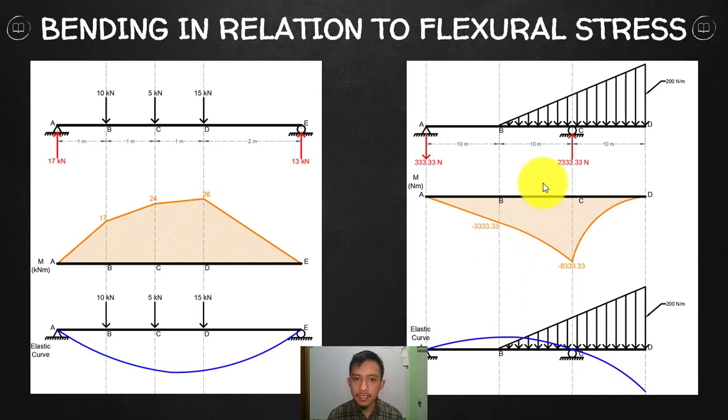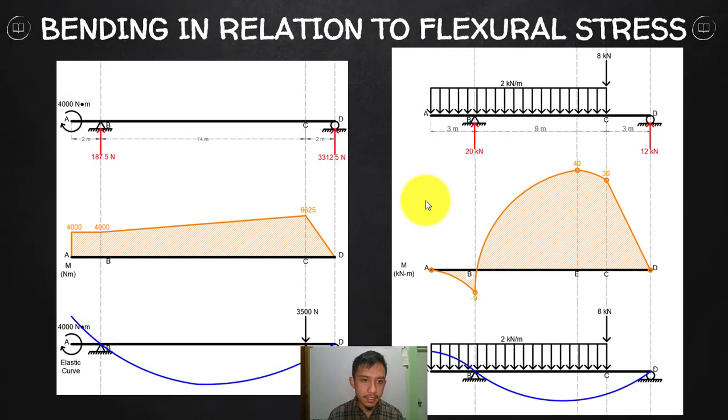So this is the simplest way to outline the entire beam. Instead of cutting and noting all the values, it is better for us to outline that using the diagram. So look at this. In this example, we have this one also. These are our previous examples. This is the moment diagram, so that will be entirely opening upward. So compression on the top, tension below.